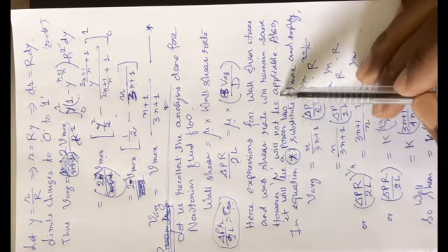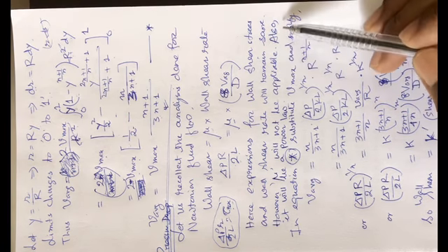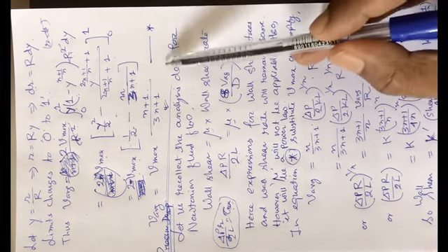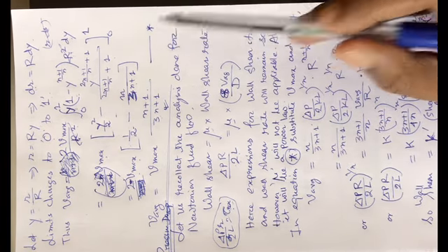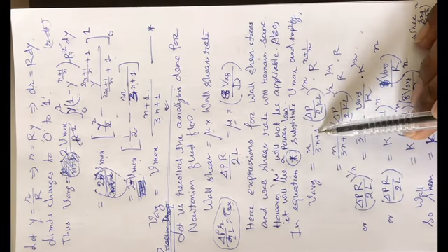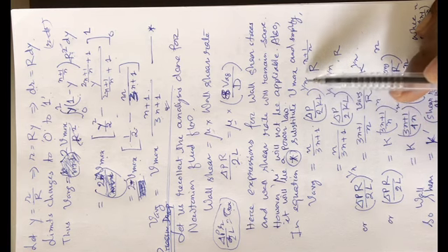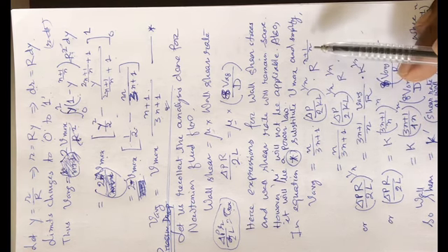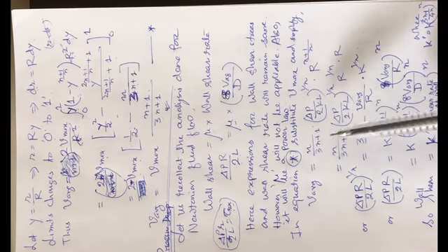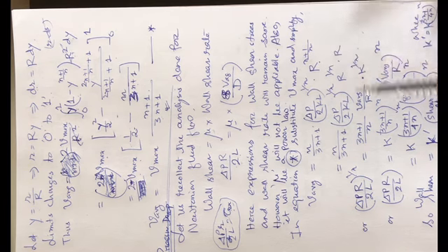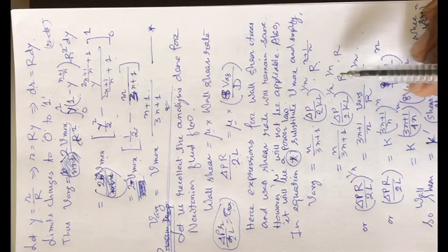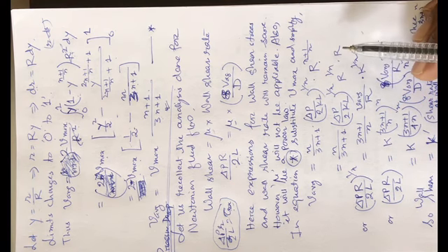So mu is not applicable in the case of non-Newtonian fluid. Another point is that it should be a power law fluid. So based on this equation we will be applying this equation. Based on that equation, V average is equal to n by 3n plus 1, delta P by 2kL to the power 1 by n, and R to the power n plus 1 by n. There we are substituting the value of V maximum, and we get this simplified expression. So V average is n by 3n plus 1, delta P by 2kL to the power 1 by n, R to the power n into R.